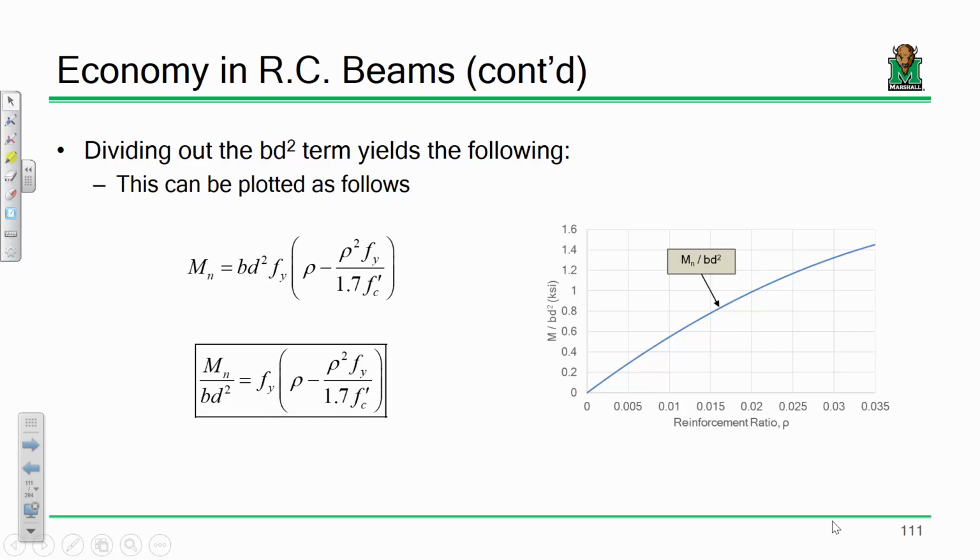So basically what I'm able to plot, everything over here on the right, is what happens to the strength of a generic beam as I put more steel into it, right? So think about that. That curve is plotting how strong that is as I put more steel into it. Now, look what's happening. The curve's going up, and it's like, well, duh, you put more steel into the beam, it's going to get stronger, right? I don't think that there's anything very mysterious about that. You put more steel reinforcement into a concrete beam, it can hold up more load. But it's not as simple as that, okay?